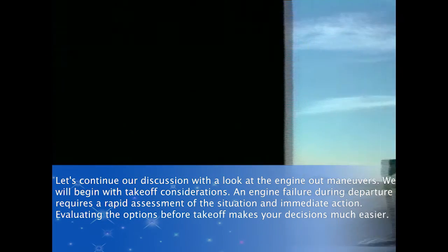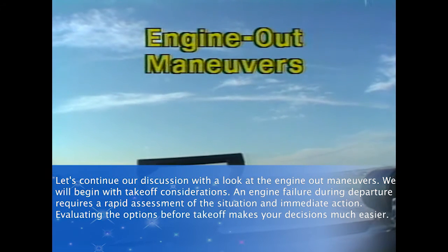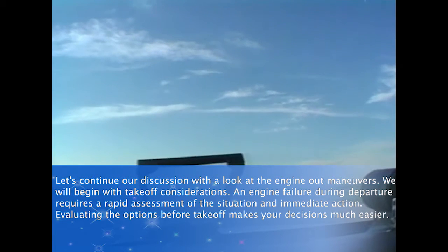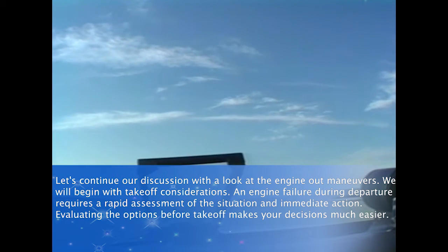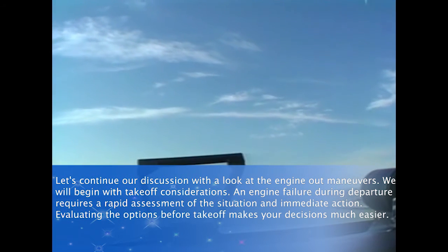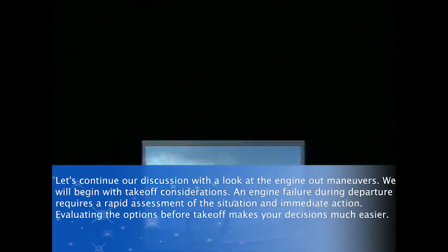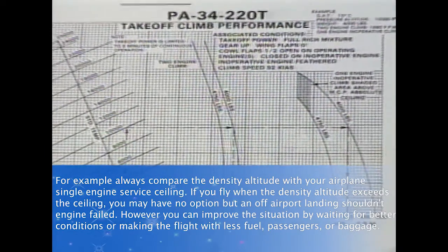Let's continue our discussion with a look at engine-out maneuvers. We'll begin with takeoff considerations. An engine failure during departure requires a rapid assessment of the situation and immediate action. Evaluating the options before takeoff makes your decisions much easier. For example, always compare the density altitude with your airplane's single-engine service ceiling.